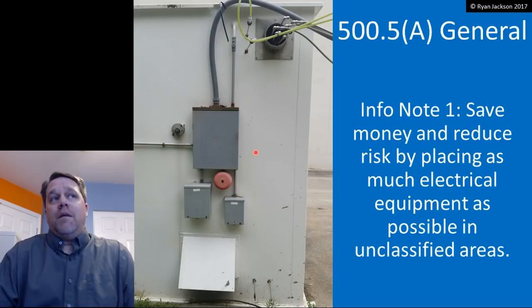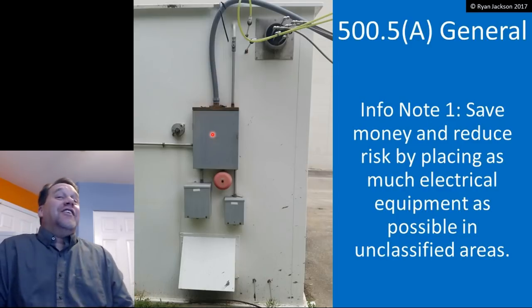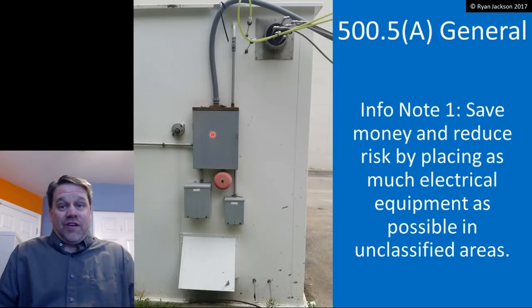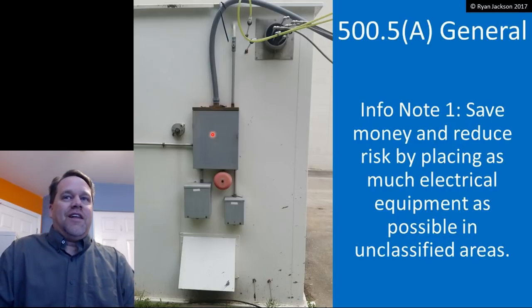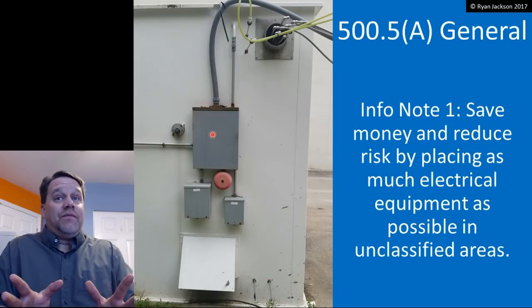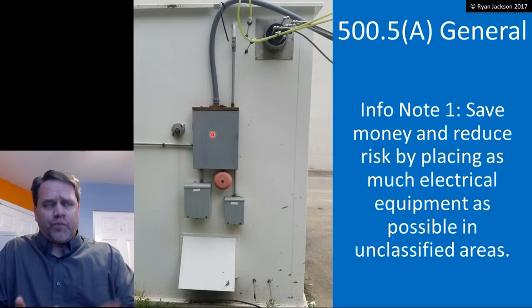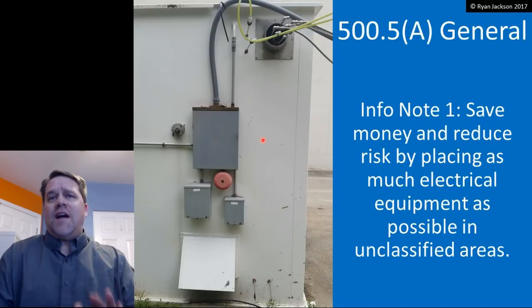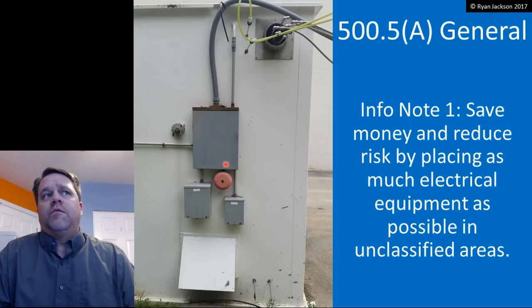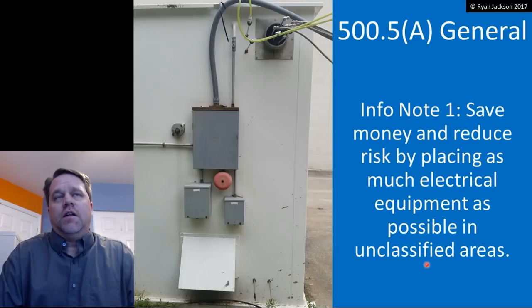Sure. You bet. They make panels that are suitable for use in a Class 1 Division 1 location. You don't buy them at Lowe's and Home Depot. You don't even go to your electrical supply house and say, hey, I need a Class 1 Division 1 panel board. No, that's not how that works, right? They make them, but boy, you're going to be smashing your piggy bank if you want to get one of those. So this rule is saying, look, save yourself some money, but much more importantly, reduce the hazard by putting as much stuff as possible outside of the hazardous location. Put it in an unclassified location.